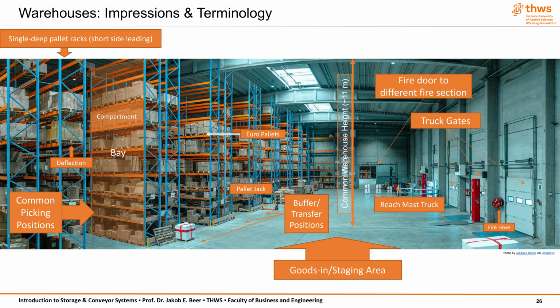From a safety and ergonomics perspective, this area must accommodate a mix of manual and mechanized operations. Forklifts, pallet jacks, conveyor belts, and, in some cases, automated guided vehicles, AGVs, all operate in close proximity. Since goods are often staged here temporarily before loading, clear zoning and floor markings help avoid misplacements and collisions. The pressure to load quickly should not come at the expense of proper handling or safety protocols.